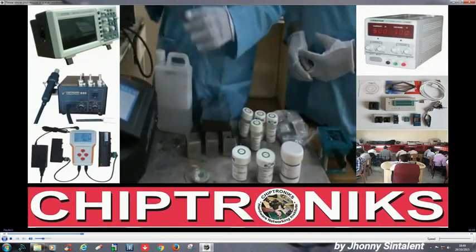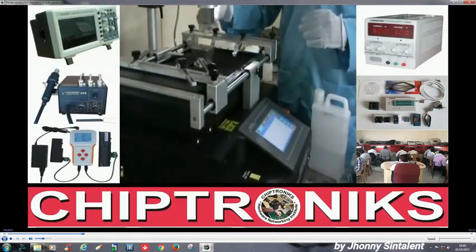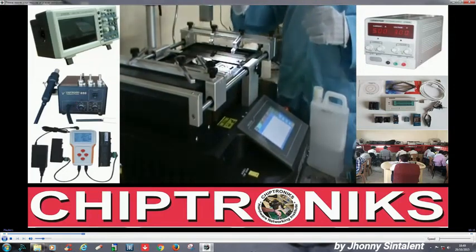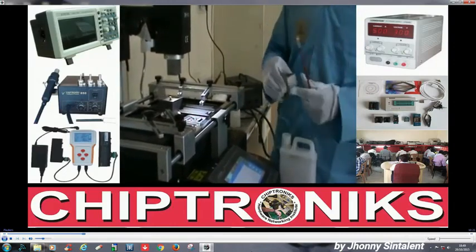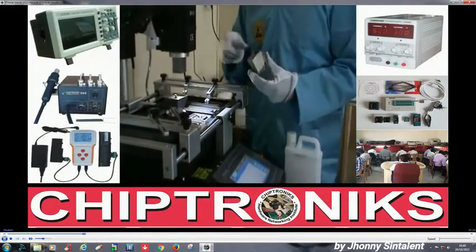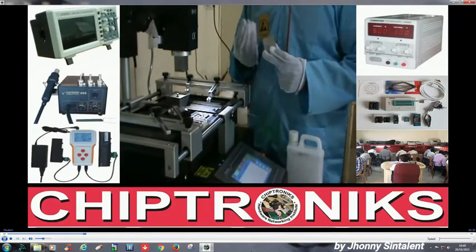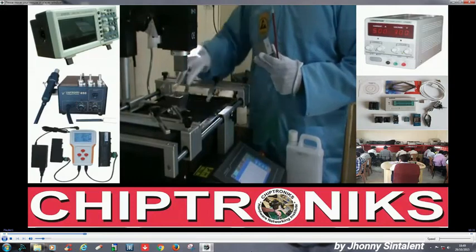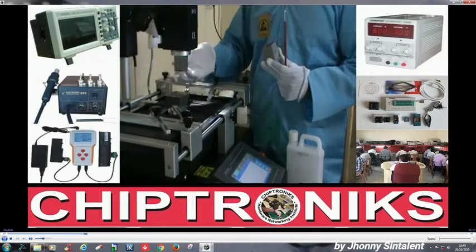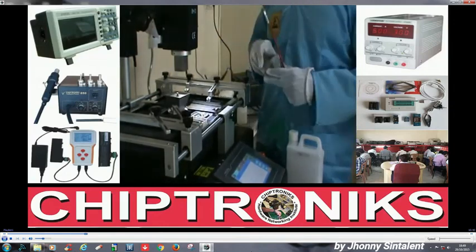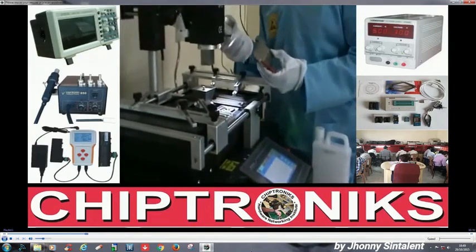And this machine will have various types of nozzles according to the type of BGA chip we are trying to remove. You can see these are removable. There are basically 5 types of nozzles, 2 for the bottom. You can see there is a hole inside this nozzle to support air flow, right? And it has a supporter over here, because this supporter will give support to the PCB from the bottom side. And there are 3 types of nozzles for the top heaters.